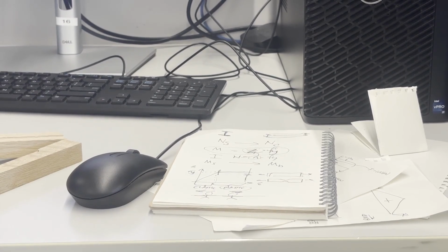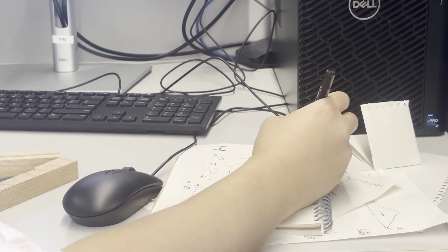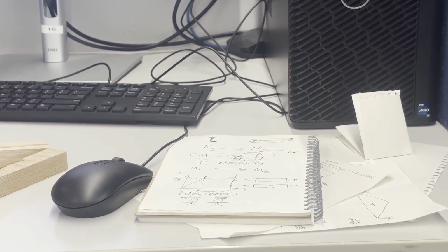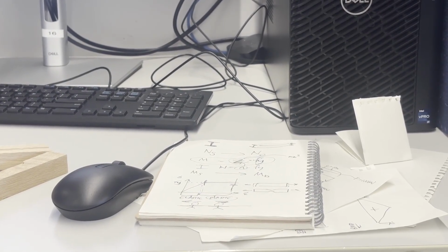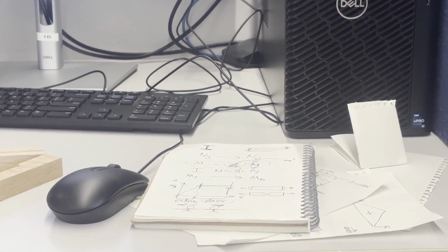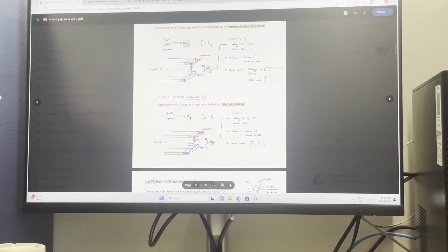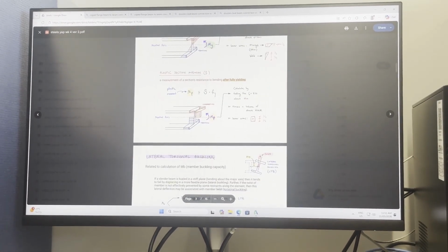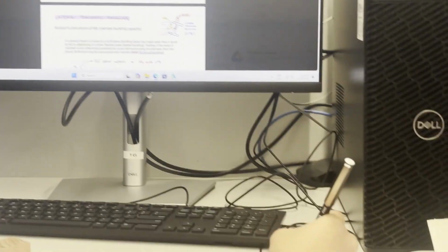It's not really the same thing, but this thing is in millimeters cubed. So it's a little bit harder to visualize, but you think of it as the equivalent of area in the context of bending. Okay, and then I explain how to calculate it, but you'll see that in examples. I just want to run through it theoretically. So that's first yield bending, right?